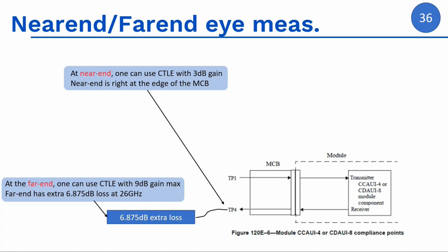The more ripples you have, the longer the memory of your structure. It's keeping information from old bits and passing it on with the new one. So the job of the DFE is to try to correct for that. That's why it's not recommended to do CTLE alone. It has to be CTLE plus the DFE.